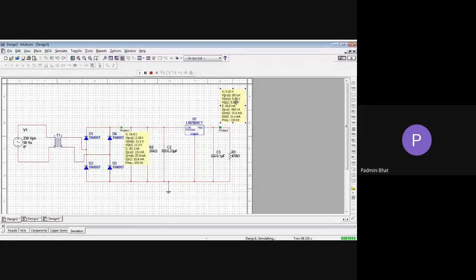If you are thinking about electronics, even for our microcontroller, microprocessor, we need these regulators because it requires a constant supply which shouldn't be altered. So we use regulators and then we give the supply to the microcontroller or microprocessor. Wherever plus 12, plus 5 is needed, next semester onwards, you will be doing your mini projects, and at that time, wherever constant voltage is required, you have to think about your regulator. Any other doubt?